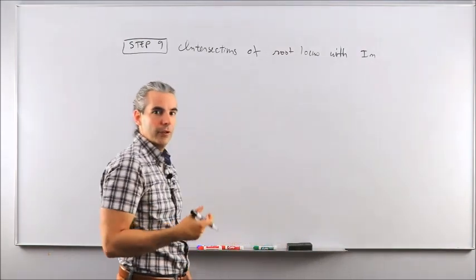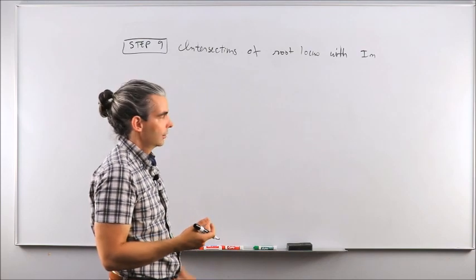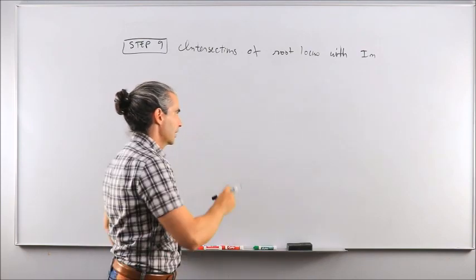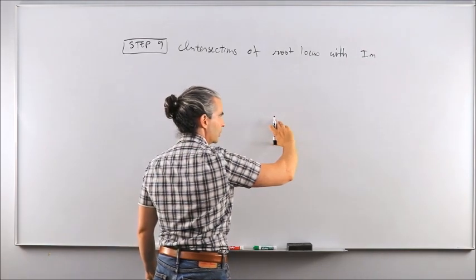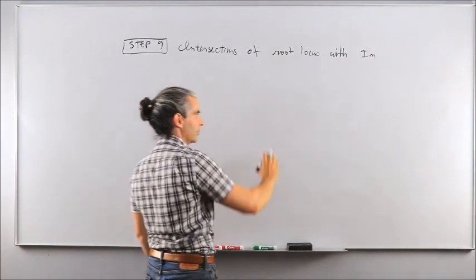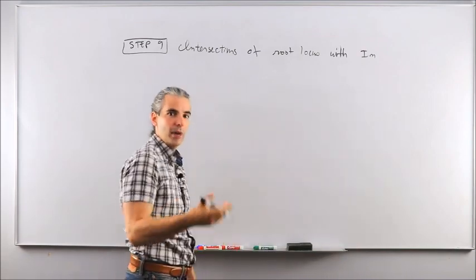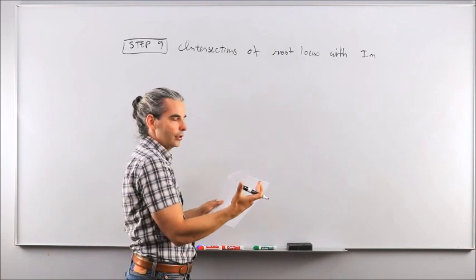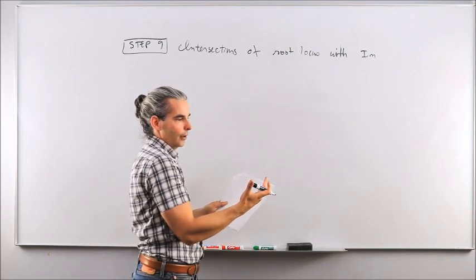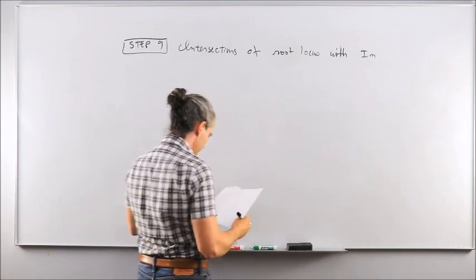And for obvious reasons, this is a key thing to consider. Or in other words, finding the limit that you can crank your open loop gain to without having the poles switch from left to right, going from asymptotically stable to unstable region, which would be a bad thing. Okay, so you want to make sure that you keep your gains in a region where all the poles remain on the left-hand side without them crossing over.